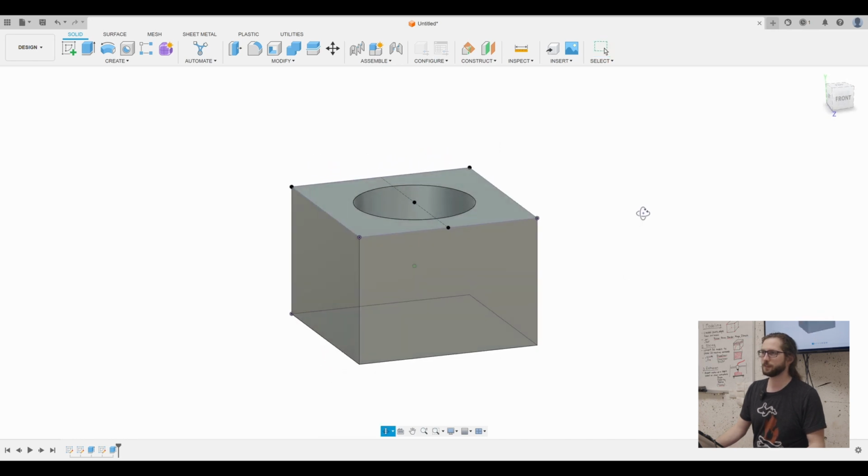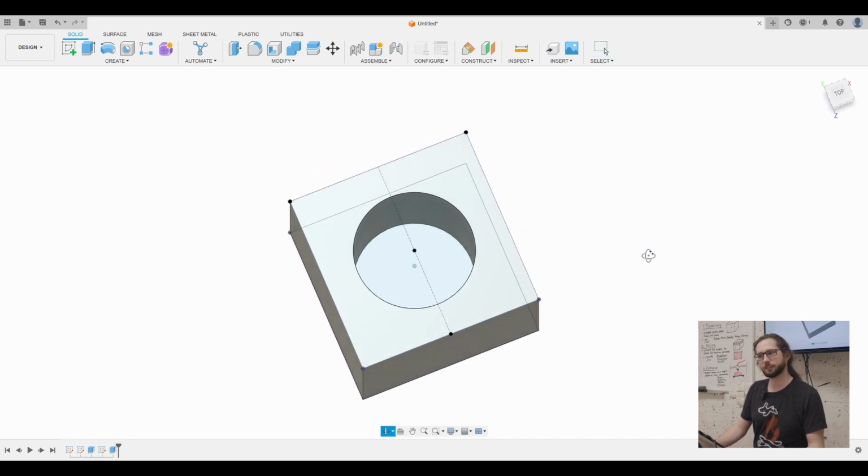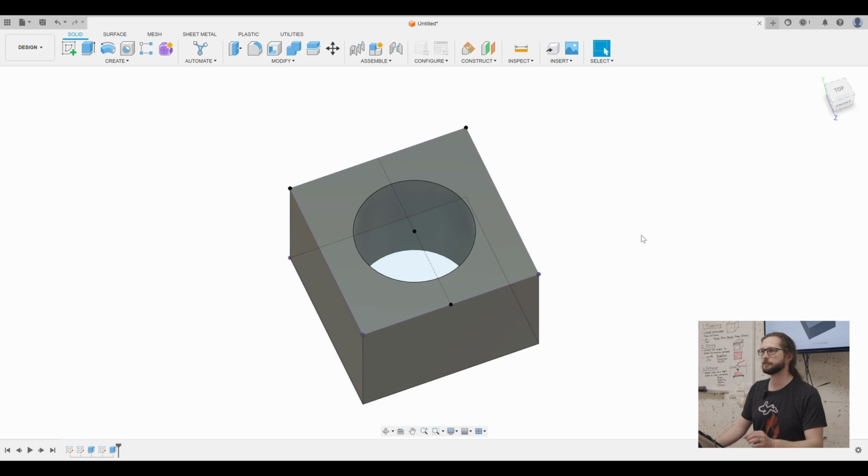And because you constrained that to exactly center, it still knows it's the center because I didn't give it measurements. I just said make it the midpoint. So it's still going to be the midpoint. In fact, if it was a rectangle, it'd still probably work. But if you placed that without constraints, then it would have just expanded. Right, so that. Yeah.